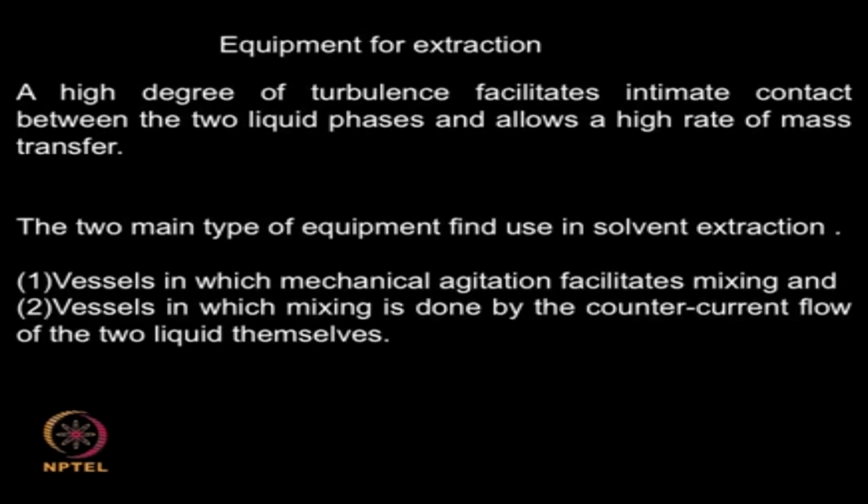There are many equipments used for extraction. In your lab, no problem, you will have something called a separating funnel. You take your broth, you add some solvent, mix them, and then leave it for separating. A separating funnel will be slowly tapering down with a bottom discharge. After mixing them thoroughly, you allow them to separate out into two layers, and then the bottom layer you remove by opening a cork which is located at the bottom of your separating funnel.